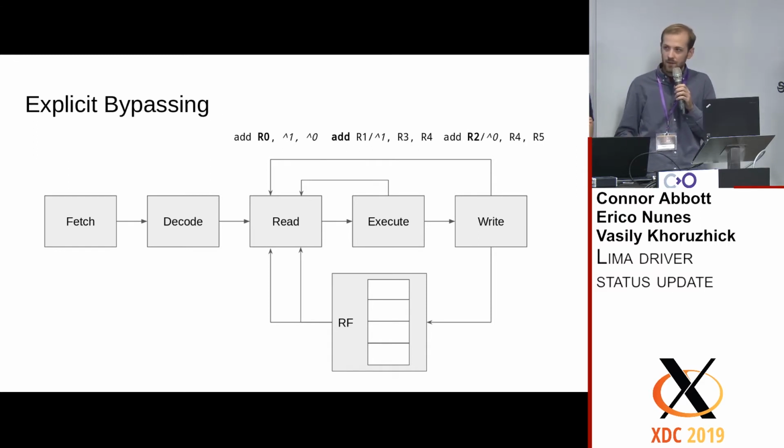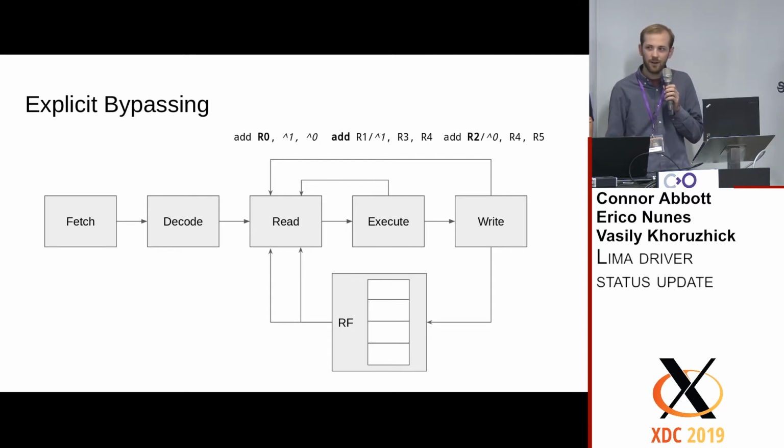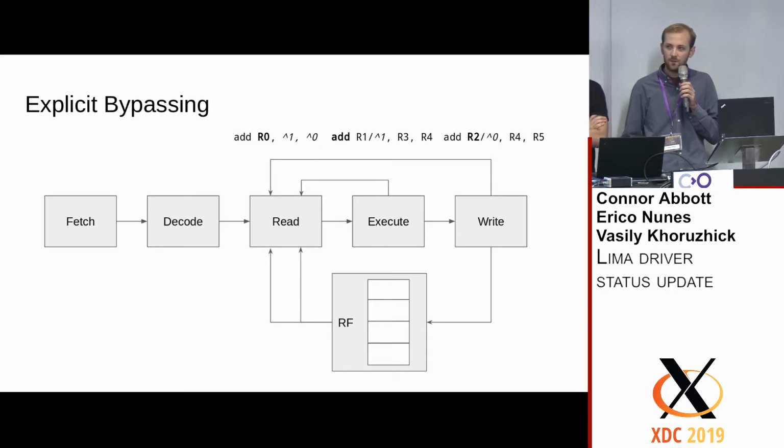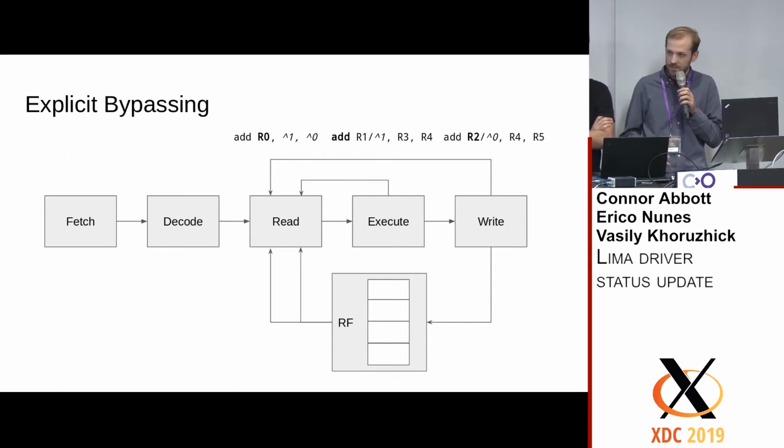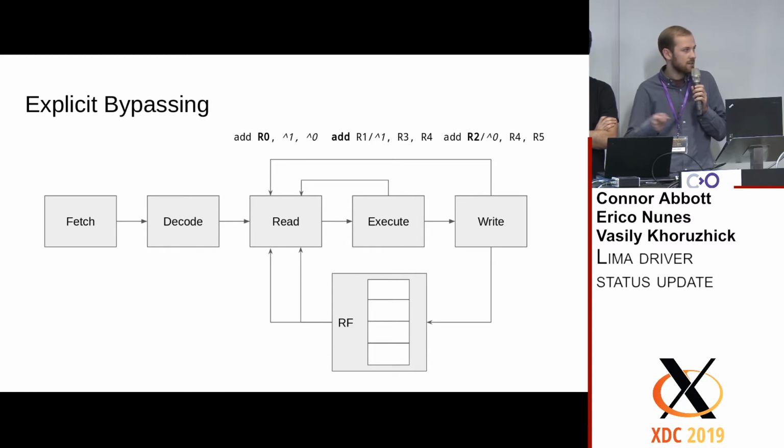What ARM does is a little bit more sophisticated. They, again, wanted to save transistors, so rather than doing this on the fly like every other CPU does, they have these pipeline registers where you basically reserve, say, 2 registers to refer to the results of the last 2 cycles. And then the compiler has to figure out when this hazard would happen and uses these special pipeline registers instead. Here I'm using the carets to represent the pipeline registers because that's what our disassembler uses, but I have no idea what ARM does internally.